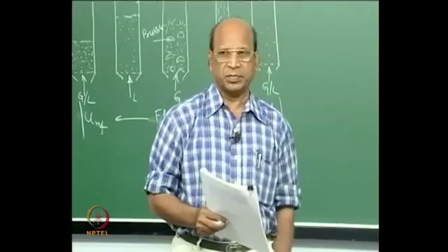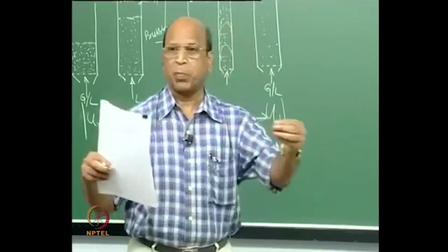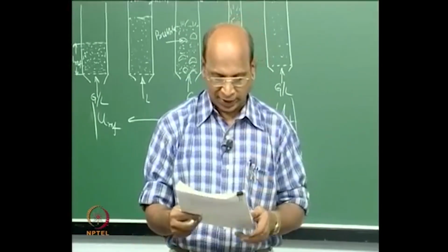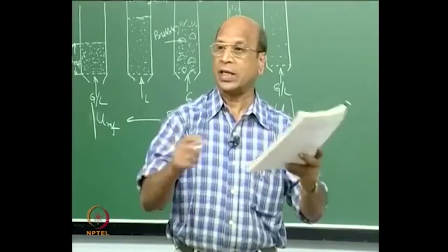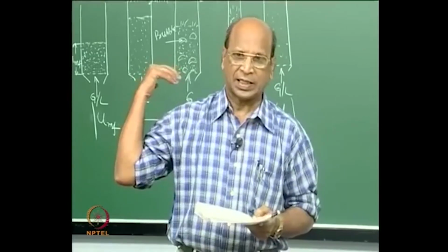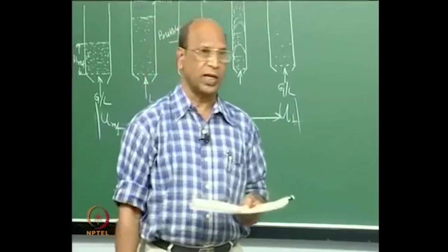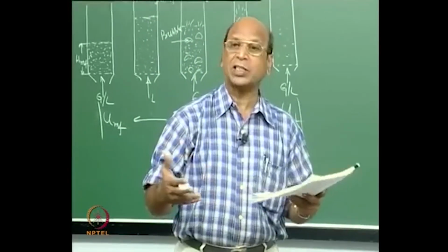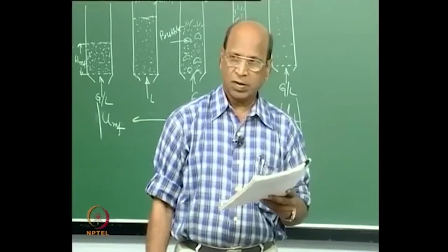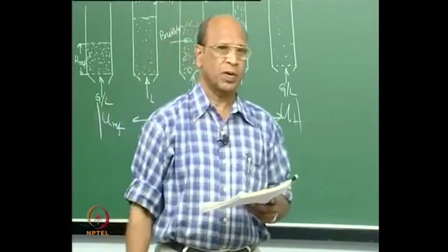What are the disadvantages? Whatever you do, there will definitely be some particle collision, and some powder will always be generated, right? So, due to attrition, that is a disadvantage. Due to attrition of solids, because we are talking about this as a reactor, the catalyst may go out, so the weight of catalyst in the bed may decrease. Attrition is one where you lose solids, right.